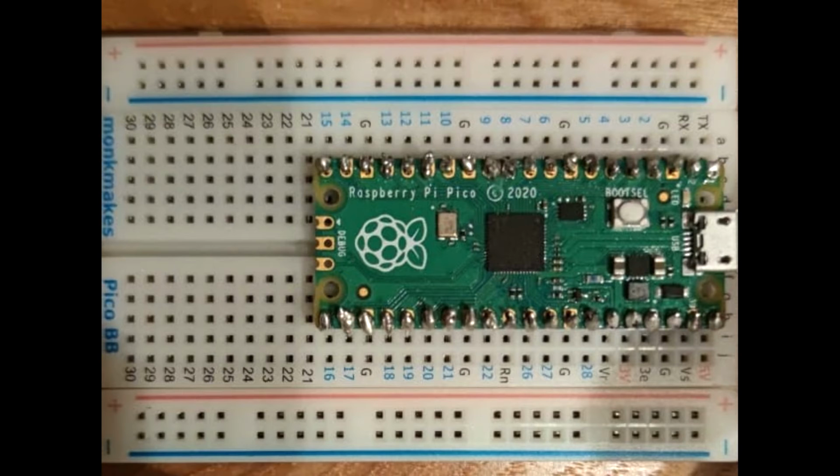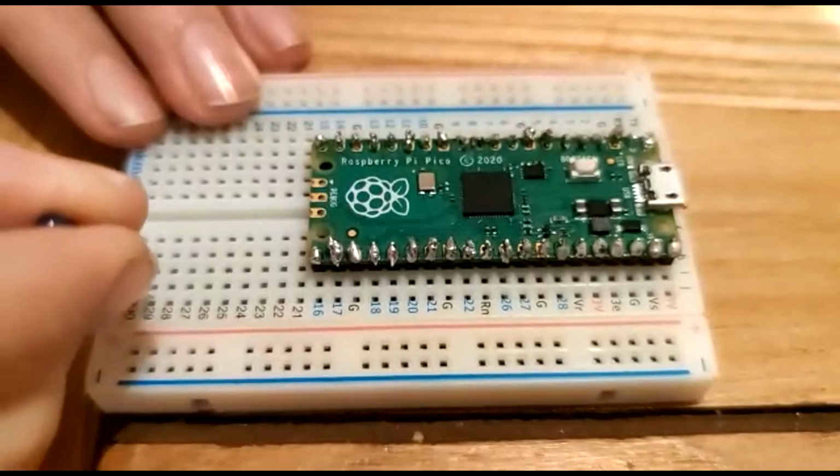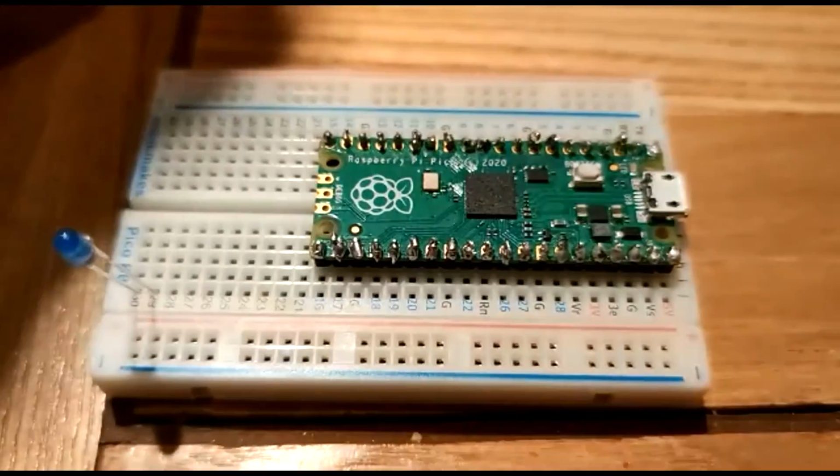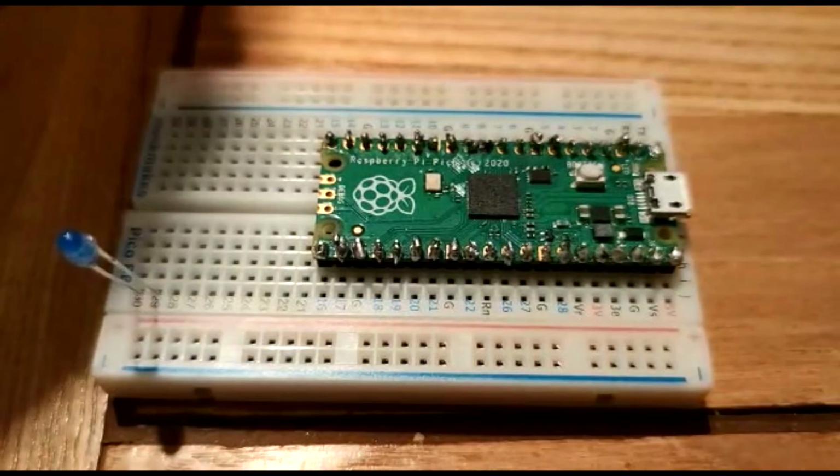Before building this circuit, ensure you unplug the Pico from your computer. Go ahead and put your LED under the Pico. Make sure that the two legs are on different rows so they are not shorted, and ensure that you remember which hole the short and long leg is in. If you connect the LED up the wrong way, it won't damage it, it just won't light up. My anode, or the longer leg, is in row 30 here, with my shorter leg, or the cathode, in 29.